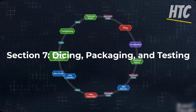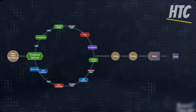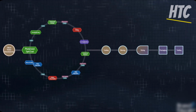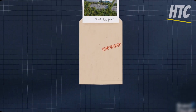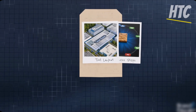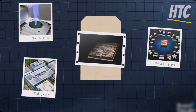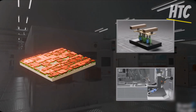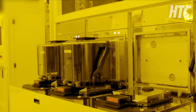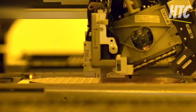Section 7. Dicing, packaging, and testing. With the wafer fully processed, the next step is to separate it into individual chips, known as dies. This dicing process is carried out with precision to avoid any damage to the extremely delicate circuitry. Following dicing, each die is packaged in a protective casing that allows for integration onto printed circuit boards. This packaging involves tiny wire bonds or solder bumps that ensure electrical connectivity.